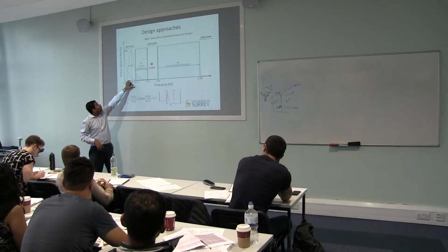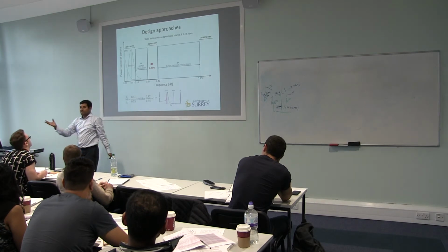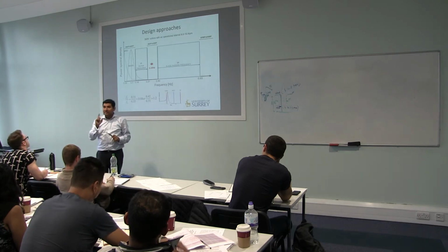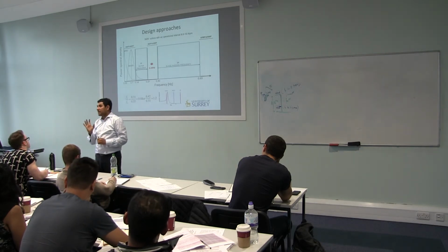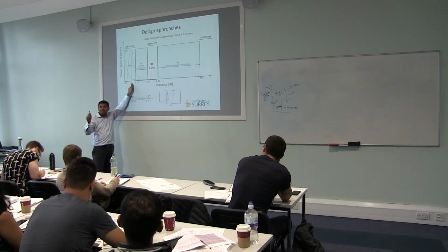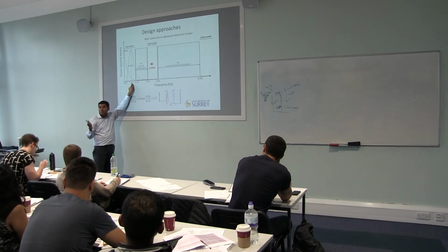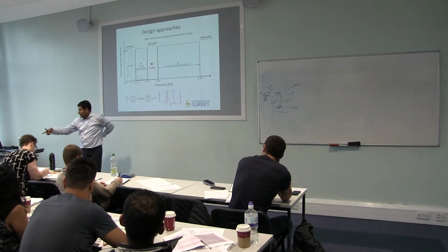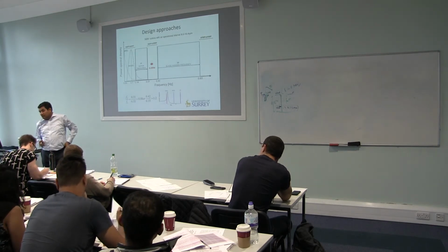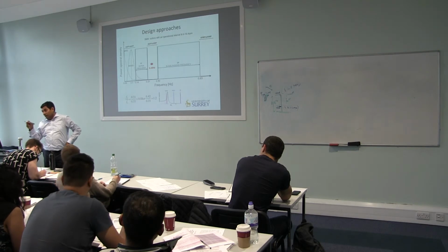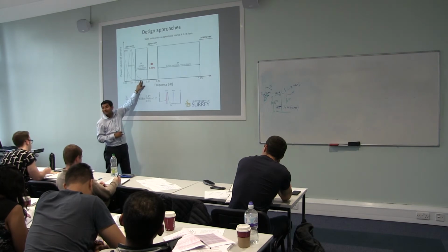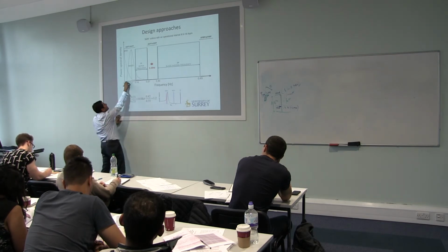The wave is a function of the sea. Chinese sea, or Irish sea, or North Sea, all have different waves. Typically the North Sea has a 10-second period, so here it is 0.1 hertz. If you look at the Chinese sea, in the chapter you will see they are like 4 second, 5 second. So 5 seconds means 1 by 5, 0.2 hertz. For the Chinese sea, this will be somewhere here, 0.2. So this is the spectrum.